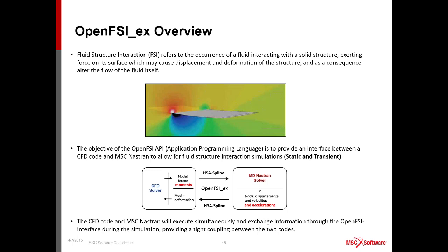Here in red and bold, I underline what we implemented in the new OpenFSI X interface in MSC Nastran 2014. So the acceleration, rotational and translational degrees of freedom, and the moments that we can pass to the structure from the CFD side.